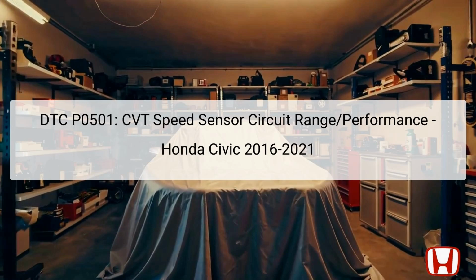The DTC P0501 indicates an issue with the CVT, continuously variable transmission, speed sensor circuit in Honda Civic models from 2016 to 2021. This error may cause performance issues with the vehicle's transmission, affecting overall driving experience. The CVT speed sensor is crucial as it monitors the speed of the vehicle and relays this information to the TCM, Transmission Control Module. Understanding both the DTC and interrelated components helps in precise diagnostics.